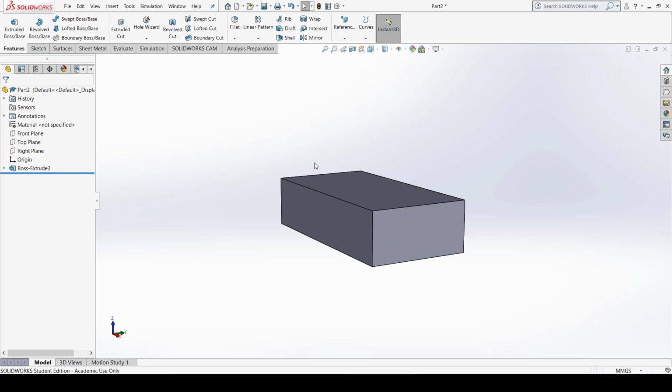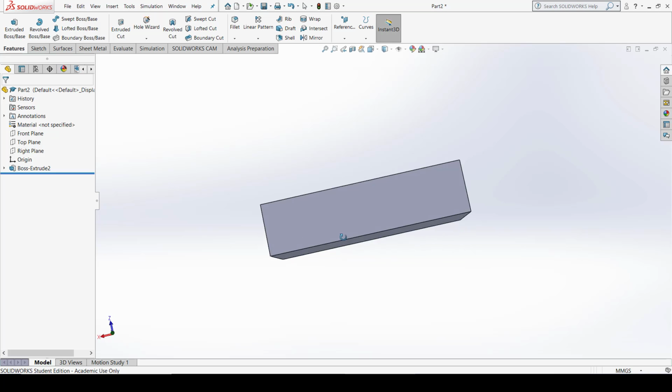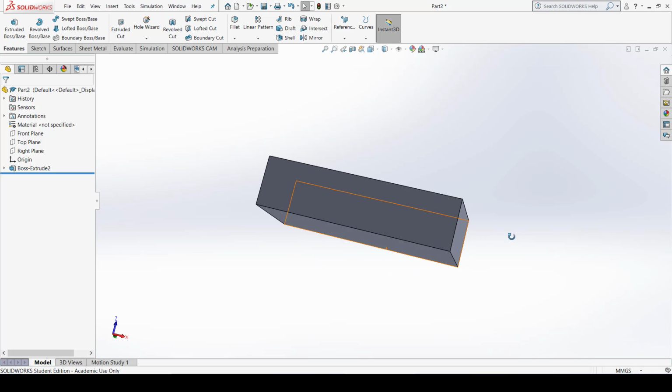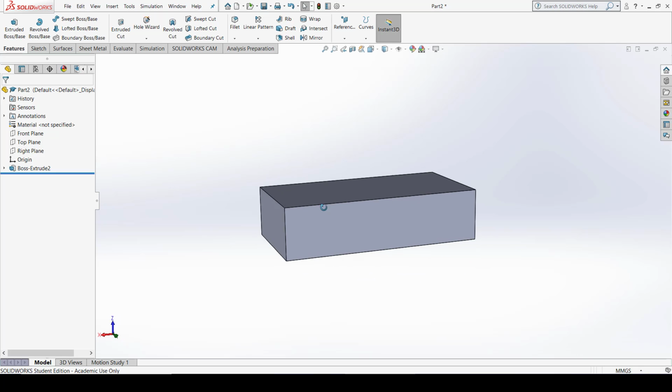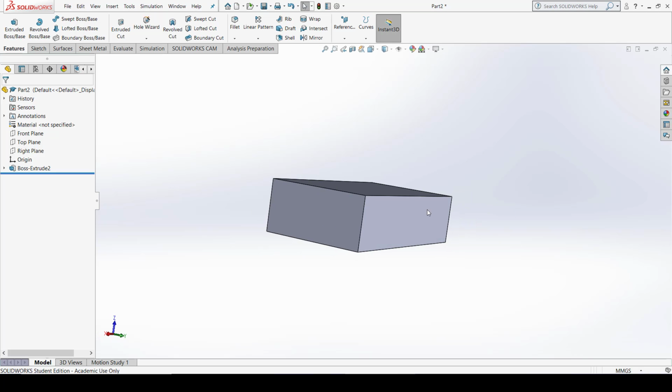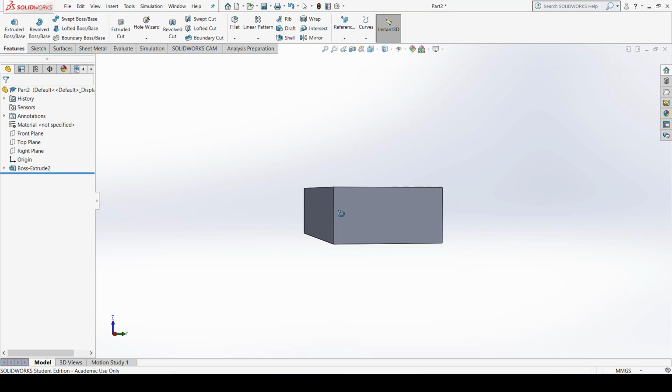Here your component is tapered, the sides of the component, let us say this is one side, this is another side, and this one is another side. So these have 4 sides, 1, 2, 3 and 4. These sides are to be tapered to a certain angle. It should be 1 degree, 2 degrees, not more than that. Okay, so a 1 to 2 degree variation can be seen.